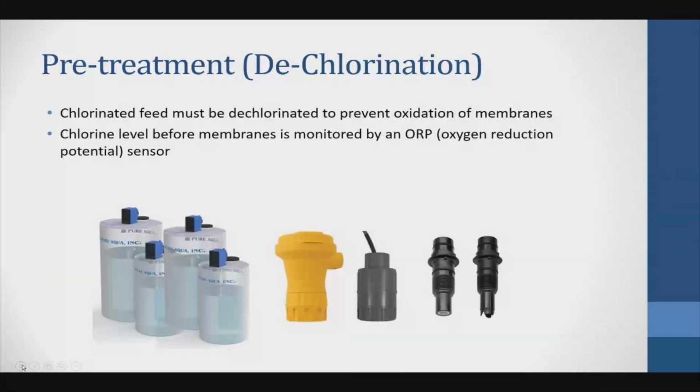Now, continuing talking about pre-treatment, we talked a little bit about the chlorination, and we said it's a good idea because it prevents causing damage to the membranes, and it would also kill any bacteria and viruses. So before that, and then we get rid of the extra chlorine.